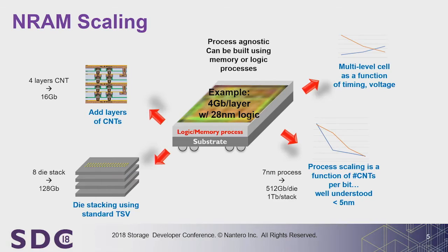I already told you that this is on a 28 nanometer process. At 28 nanometers, we have some 2,500 carbon nanotubes switching per bit. But I said all we need is 100. So if you do the testing or the modeling down to the finer geometries, who could guess where 100 nanotubes is? Turns out that's a 1 nanometer process.